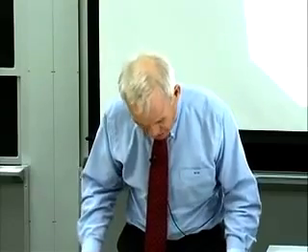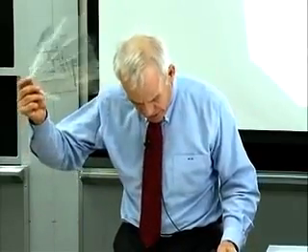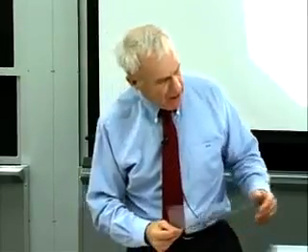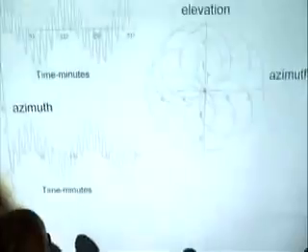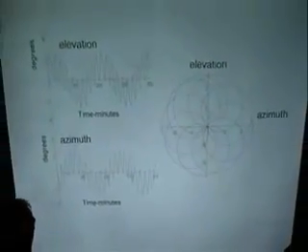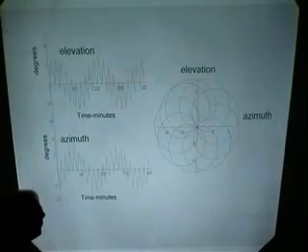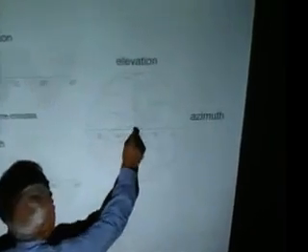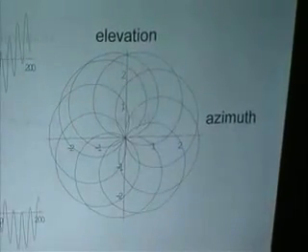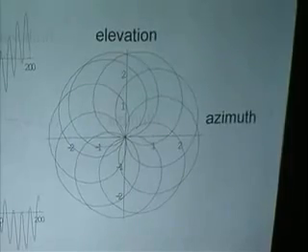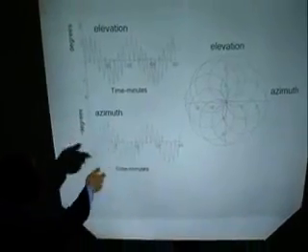With that initialization, and I'll come back to the idealized two inertias equal case, you have a motion that now has its angular momentum vector right there along that x-axis where you applied that torque to spin it up, and you get this looping motion, because the x-axis isn't